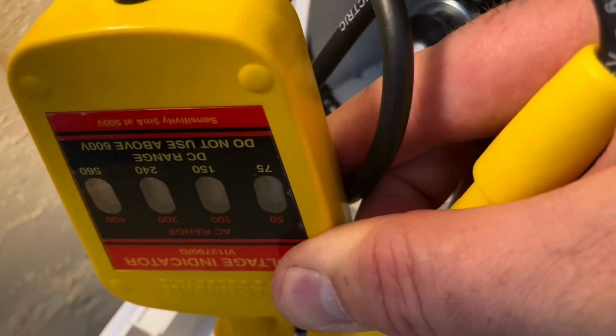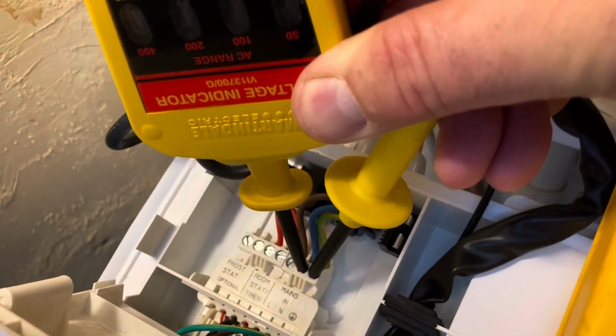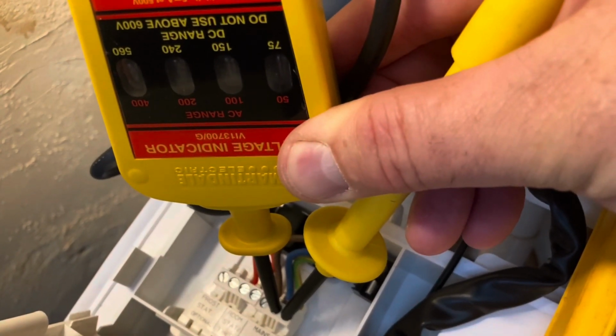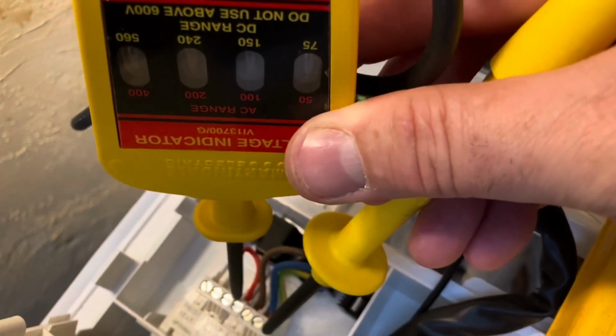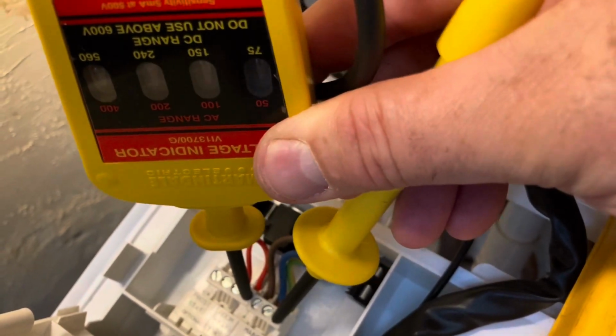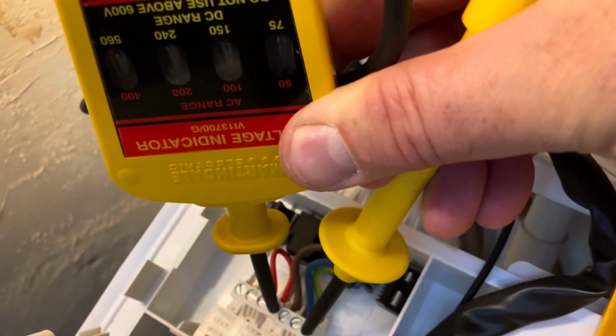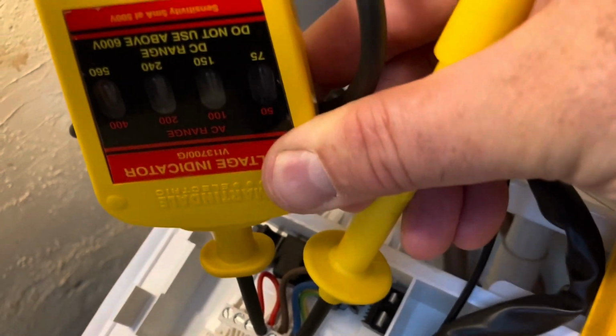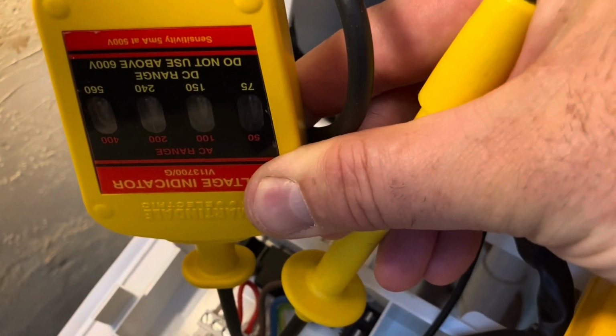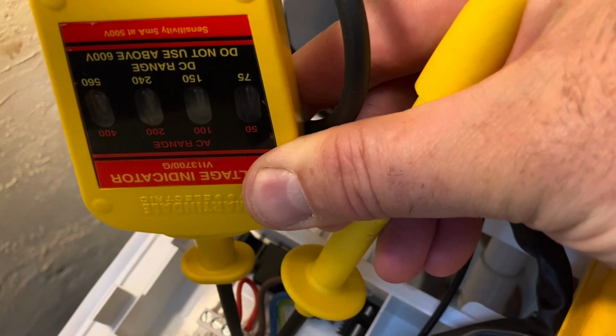It's very difficult with one hand. Neutral to earth, 0 volts. And then any incoming switch lights, room stats, pump lights, anything else coming into the boiler, we also want to go across those to make sure they're not connected to a different power supply. So go across any other incoming cables. This has got a link in, but I'm just showing you that that is also 0 volts.